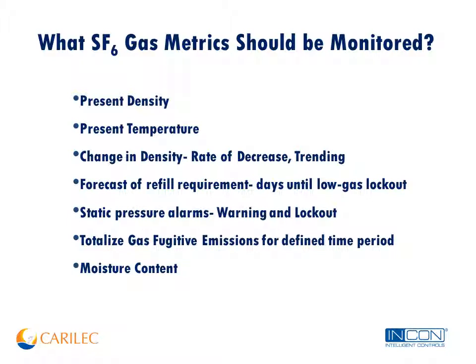Well, for us, we think it's important to measure the density of the gas. Density is a measurement that's independent of temperature and pressure. It's a measure of the amount of molecules in a given space. So we use a very sophisticated new sensor that monitors density directly. So it's very accurate and minimizes false alarms. It is nice to know the temperature, if for nothing else to know the cabinet temperature where these are usually installed. So we'd want to take this data and calculate the change in density, which would give you the rate of decrease and trending of any leaks.